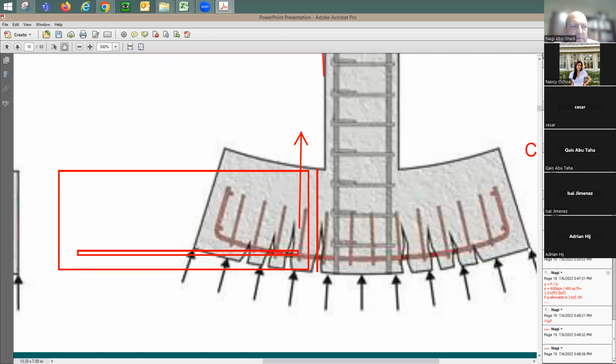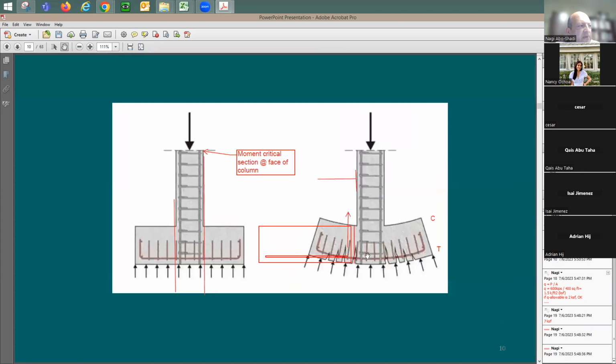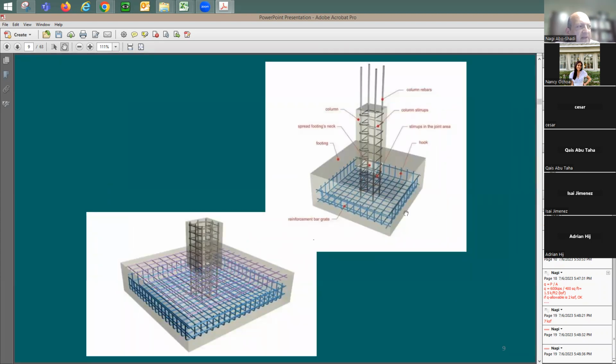When you size the footing, it means length and width, like here in plan view. You size it based on the bearing capacity of the soil itself. The bad thing that may happen is if the load coming to the footing is above the allowed bearing pressure, the footing is going to start to settle, which means it's going to start to penetrate the soil.